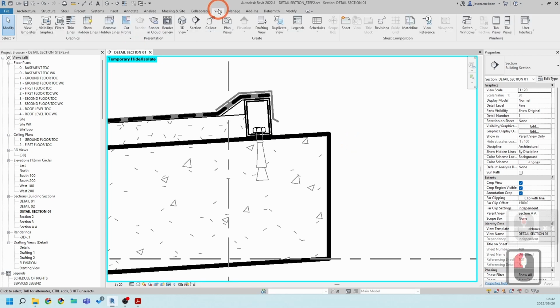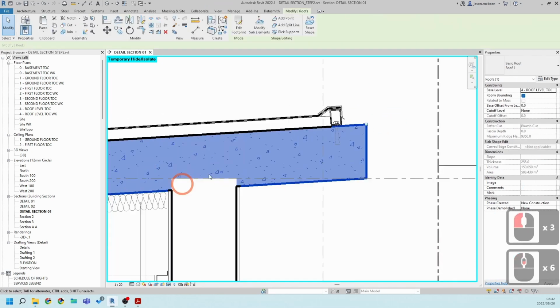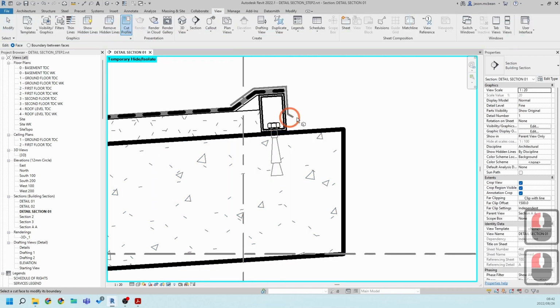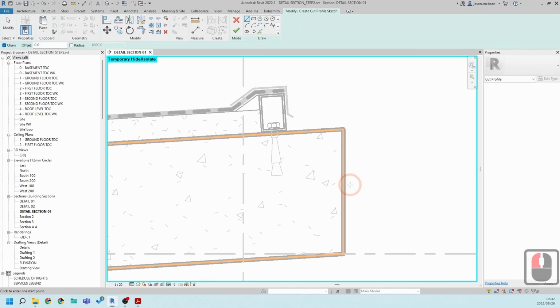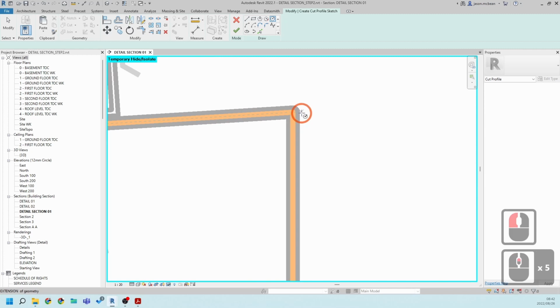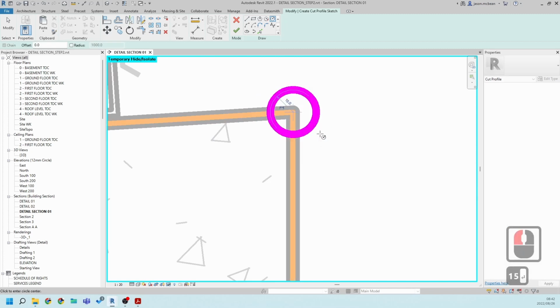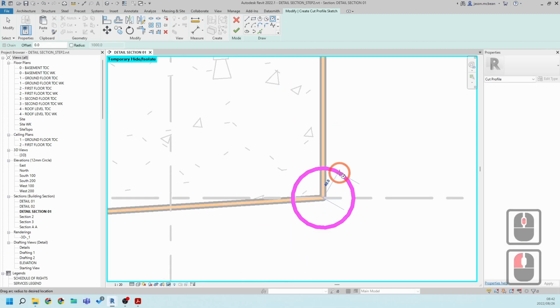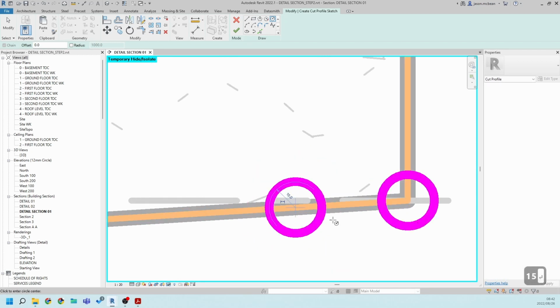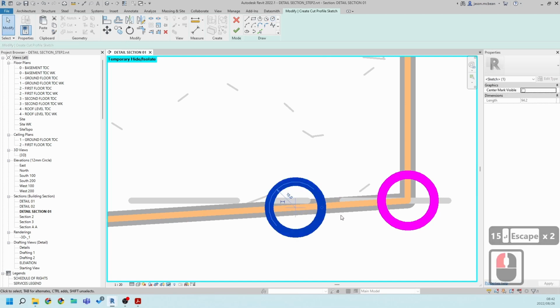If we go to view, so select, this is a modeled roof. This is a 3D element. So what we're allowed to do now is go to modify roof and then go to the view tab, where there's an option here, cut profile. This allows us to modify this profile in this view only. I'm going to use circles, and I'm going to use a 15 mil. I'm going to use some chamfers over here, 15 mil. And the last one I'm going to do is create this 15 mil, because I need to show this drip joint.